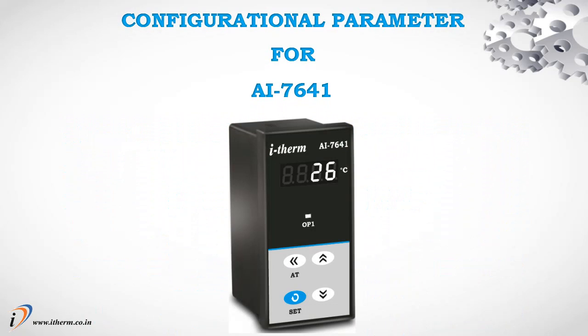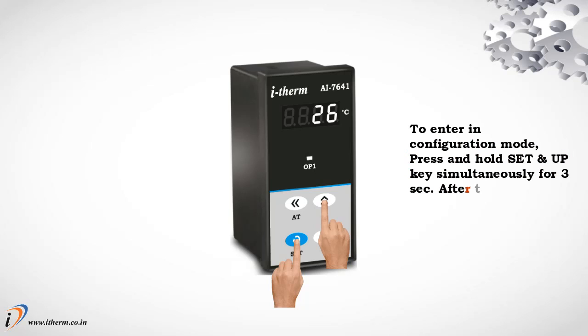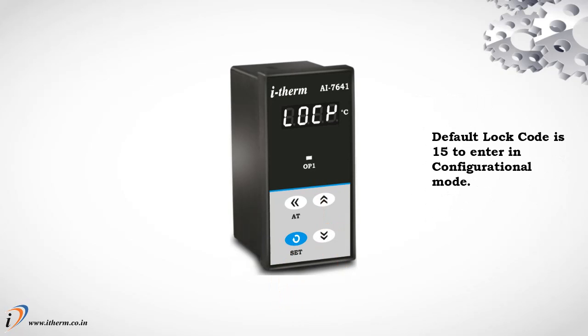Configurational parameters for AI7641. To enter configuration mode, press and hold the set and up keys simultaneously for 3 seconds. After that, the lock code will appear. The default lock code is 15.